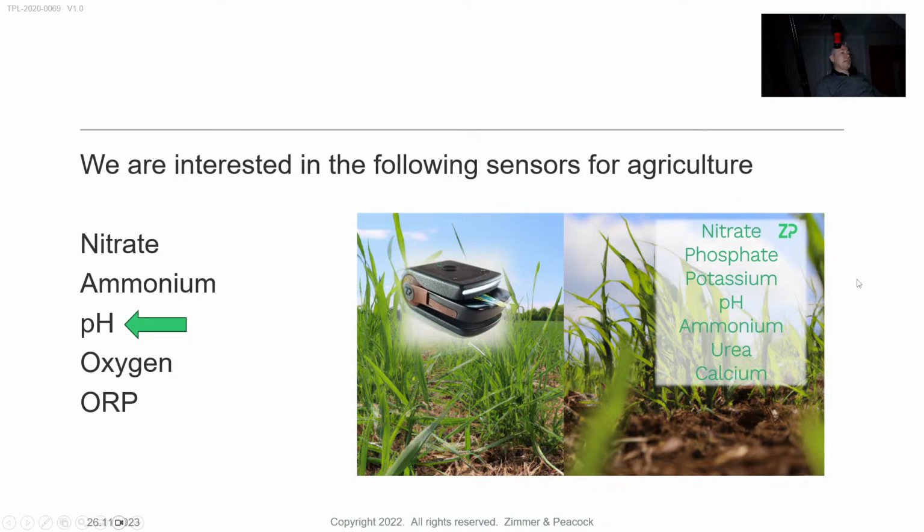At the moment, they've got the pH sensor. Don't worry about the shelf life. Those pH sensors are really quite robust. So I wouldn't be super concerned about, you've got the pH sensor good. Is it going off? No, I doubt it. Unless you're leaving it in direct sunlight at high temperature, I suspect you're not, and therefore it should be okay.